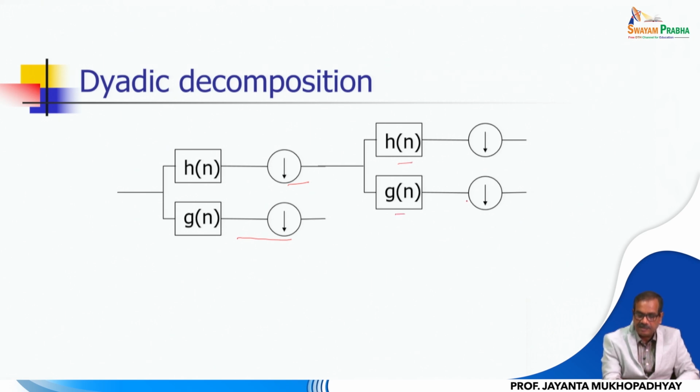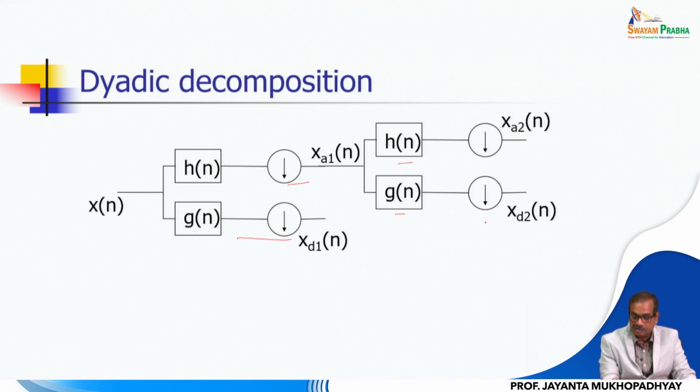So this is the form you can do, and then reconstruction would be in the other way. You can also get the reconstruction. So this is the approximation at this resolution. This is the approximation at this resolution. So these are the representations which are finally retained for representing the signal. And while reconstructing, once again you can use a synthesis filter for reconstructing this resolution XA1, and then another synthesis filter for reconstructing Xn.